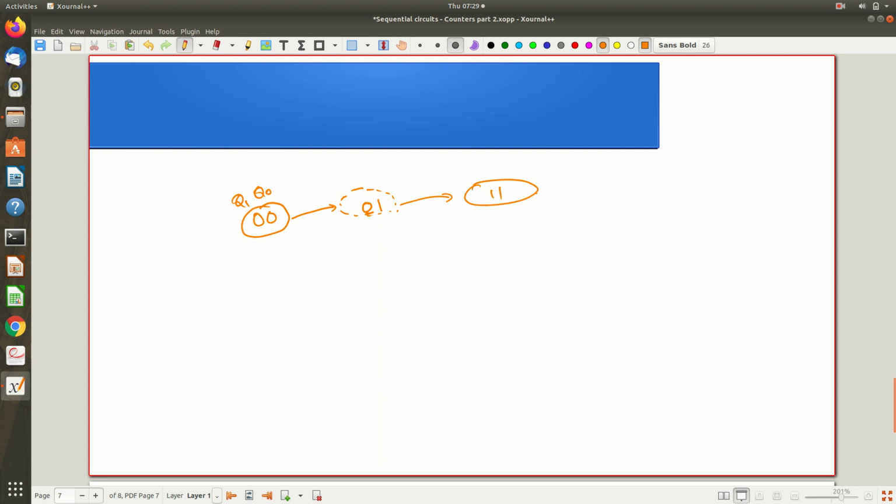Okay, fine. Now what is the next state? Next state is this Q1 toggling to 0, but what about your Q0? Q0, that 1, it is retaining, so there is no issue. Whenever there is toggling, that time only that delay is going to affect you. Next that problem will happen because your Q0 is changing to 1, but Q1 is supposed to change to 0 because of the 0 to 1 transition, but that will happen only after a small duration of time. Till then it will retain this 0, right? This is something we don't want. It's supposed to toggle, but it will retain that 1, so that is a problem.